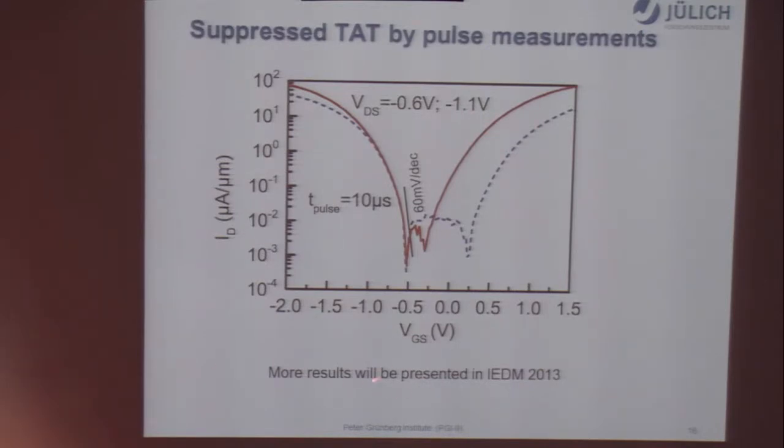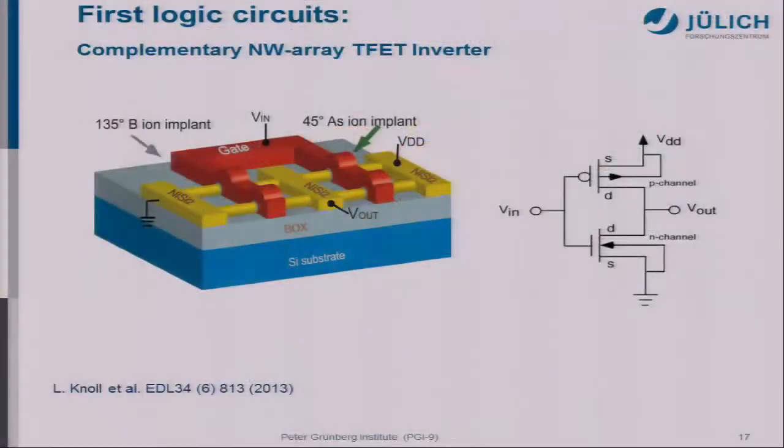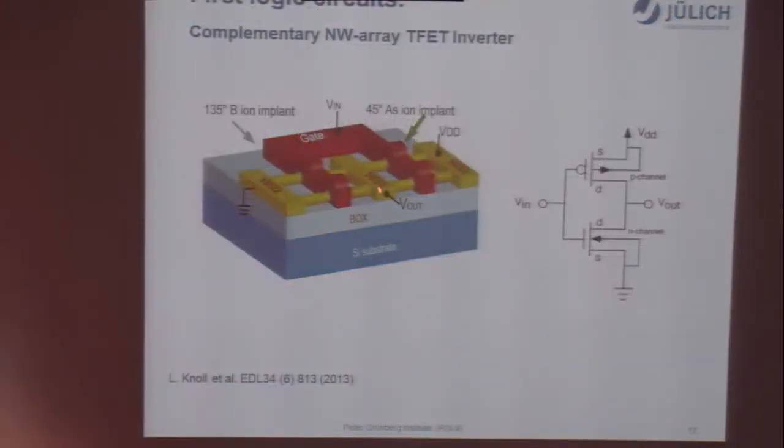More results will be presented at the IEDM this year. Also using this technique, we can easily fabricate inverter structures. You see here, we have two gate fingers, and we do the tilted implantation of boron and also arsenic. In this case, we form the NFET on this side, and also the PFET. This is tied with the common drain as the output contact.